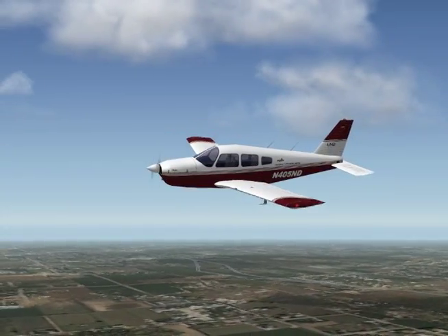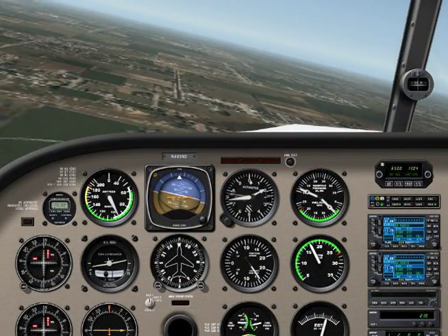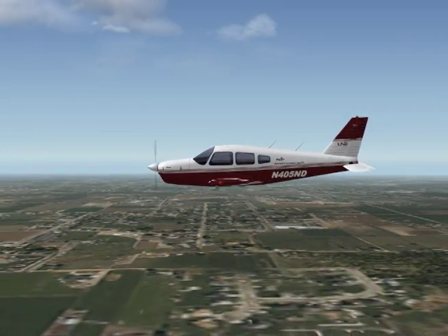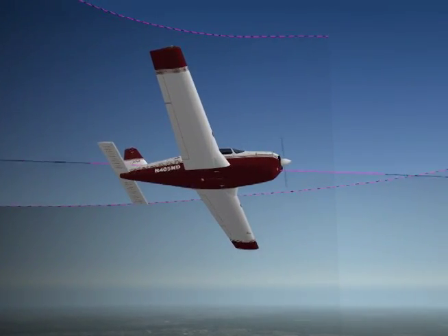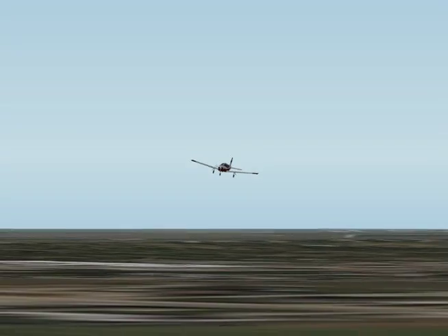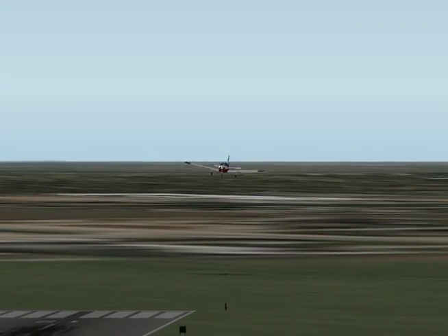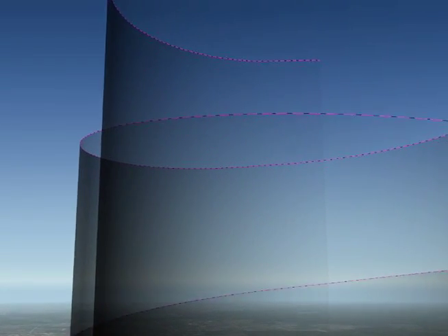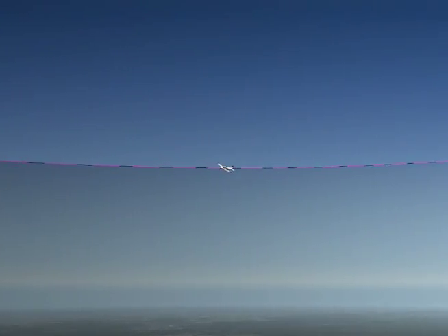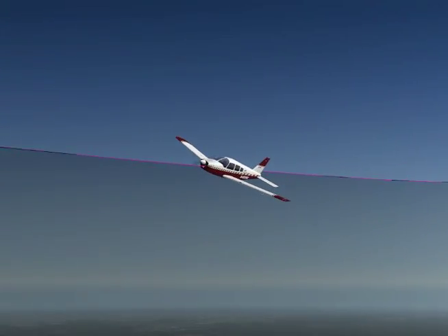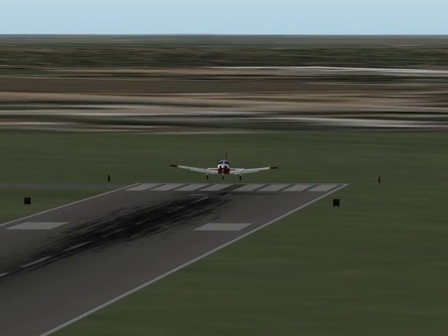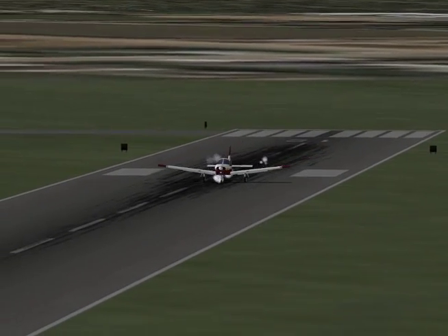Finally, as the third turn is being completed, the pilot can roll out on a pre-selected heading which would simulate a pattern entry to a point on the ground where a forced landing could be made. If on a dual flight, the student may perform a gliding turn to an airport where a power-off landing can be made. Remember, a spiraling descent over an airport must be completed while making applicable airport radio calls in order to ensure traffic separation. It is the pilot's responsibility to see and avoid all traffic during the entire spiraling descent by dividing attention in and out of the cockpit.